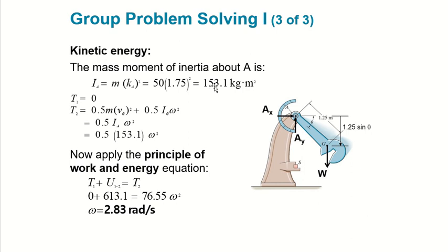Multiply that and you will get 153, and this is your equation in your textbook that you see. I already showed you that in the previous slides. So you put them all together and you will get that. Starting from the rest position, kinetic energy is 0 because the velocity is 0, and your final kinetic energy is your translational and rotational, because it's translated and also rotated. So we go back to our translation, 1/2 mv², and then your rotation, 1/2 I omega squared, okay?